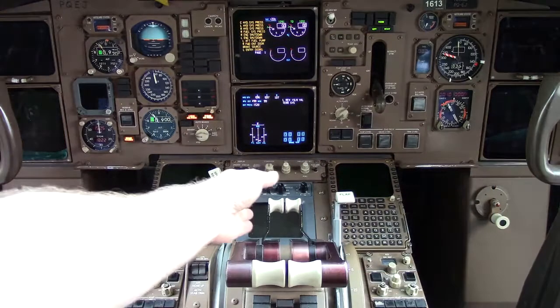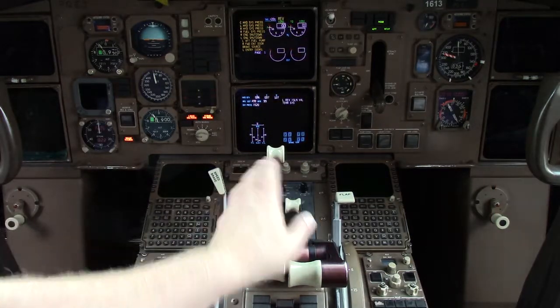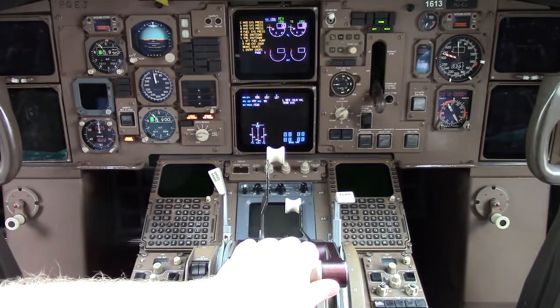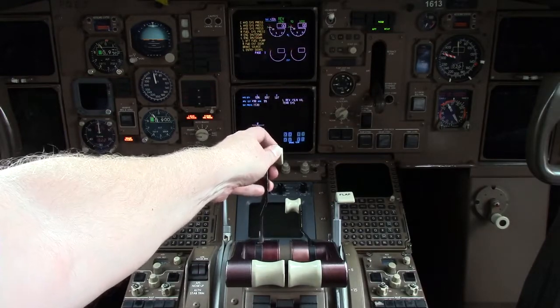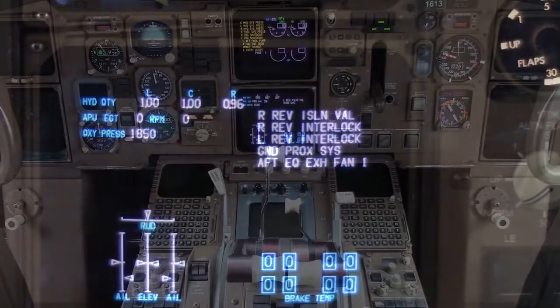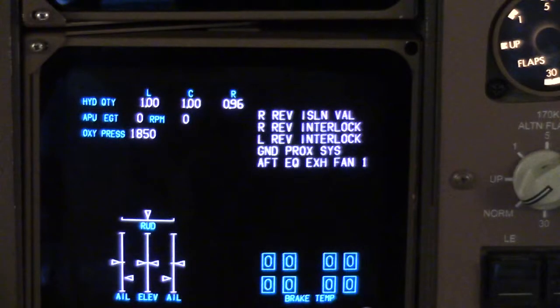Thrust reverser interlock actuator. The purpose is to make sure the throttle does not pass through the idle detent until the thrust reversers are extended. The interlock actuators are controlled by the EEC. If the actuator fails in the retract position, the throttle will not advance past the reverser idle position. No ICAS message will appear. A left and right interlock message can appear to alert the flight crew of an interlock failure. The throttle can move past the reverse idle detent before the thrust reversers are fully extended.